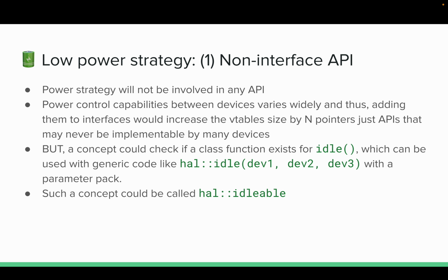I don't even know if those devices are so simple in their design and how you set them up that there actually isn't even a way to put them into low power mode besides killing the power completely from them. Now, luckily they don't have any state either, so it doesn't really matter if you powered it off and powered it back on. You'll just maybe have to wait a little bit for the setup and hold time from reset till the actual analog values have stabilized. That'd be pretty much about it.